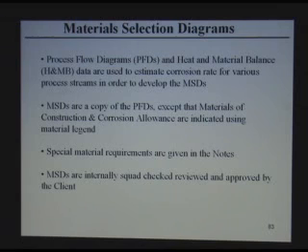If you have H2S, what is the partial pressure of H2S? Does it have hydrogen, no hydrogen, etc.? And then we start estimating corrosion rate based on the curves I gave you before. And based on that, you start selecting materials.